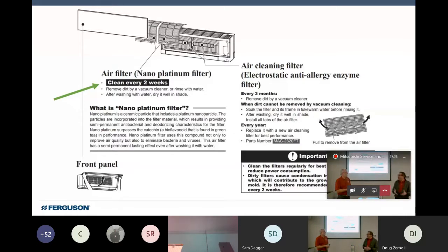So the amount of air exchanges taking place is twice that of a gas furnace or an air handler. So yes, asking a consumer to check these every 2 weeks during operational times, which for most of them now, being heat pumps, is all year long, really needs to be done. And it's right there in their operation manual, so it's not just you telling them. But I would point it out when I'm going through my checkup or turning the unit over to a customer, I would be showing them this.